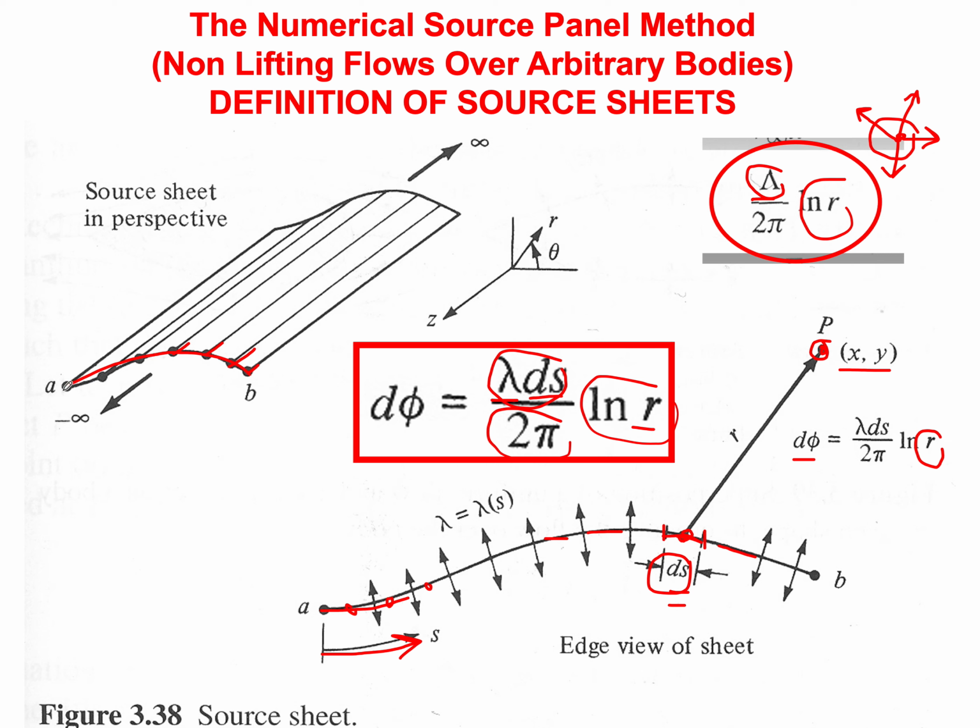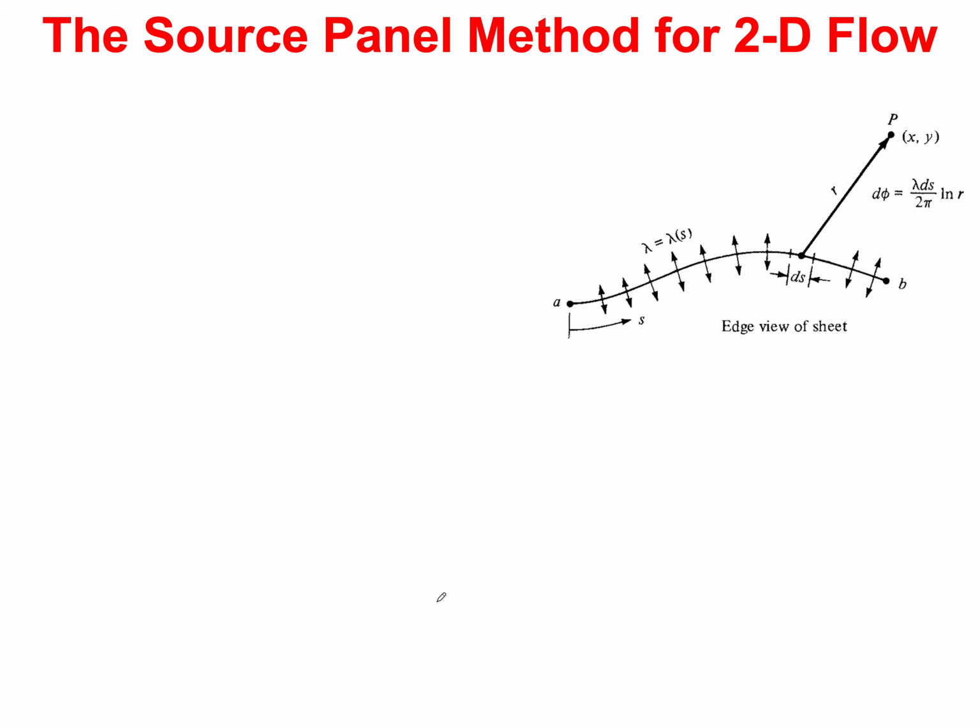So if we have a surface AB, what we want to eventually generate is a streamline that looks exactly like AB, and what we do is we distribute an infinite number of sources and sinks along that line, such that in the end AB would also be a streamline. This S direction is also a streamline, so that the velocity is only parallel to that line, tangent to line AB along the S direction.